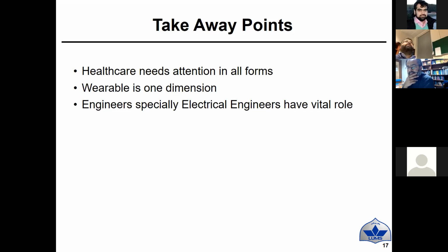What I can tell you is our design cycle. We do a first prototype so that we get some confidence from the local doctors and get their vetting. And then we go for IC design. We go for a very small system, and then again, that is a lab version. So the IC design process takes 1.5 years, since you need to do the design, then you send it for fabrication, then the chip comes back, you do the board, you verify it, and you make sure everything is working fine. And then if everything is fine, then you can go for, let's say, commercialization.